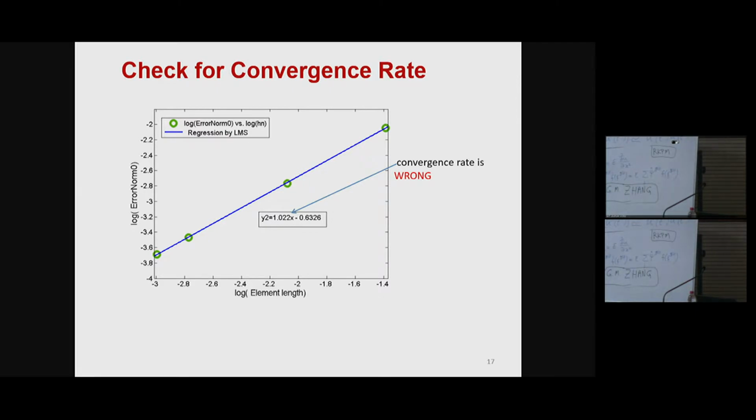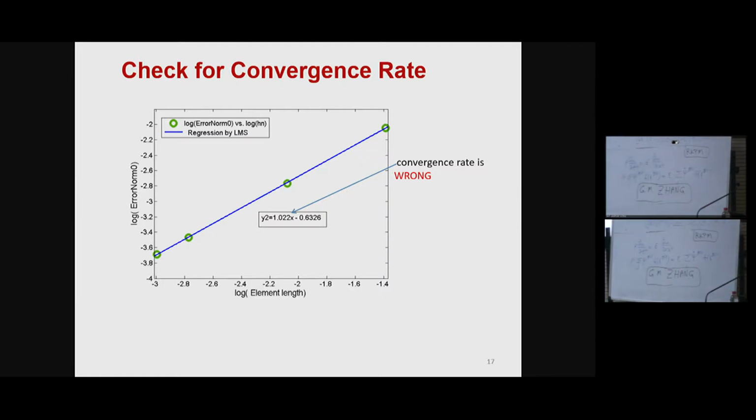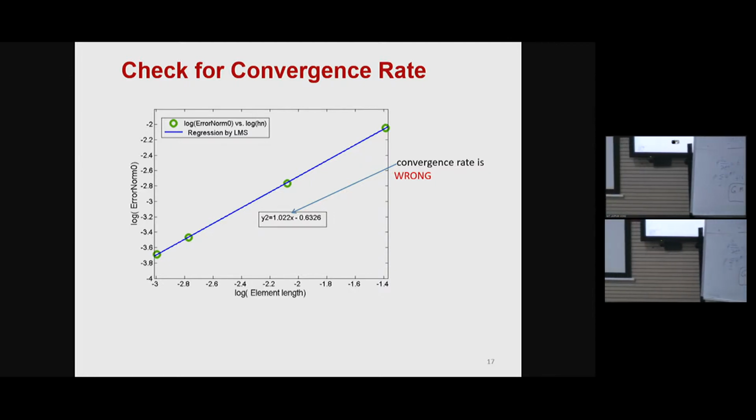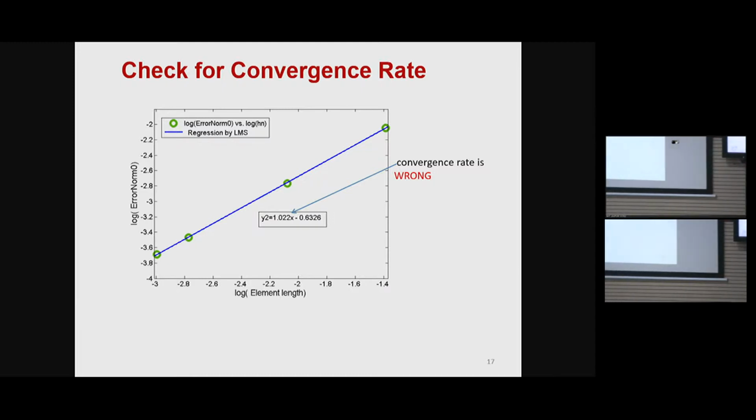The critical edge. Well, I don't know what is critical, but whether it's critical or non-critical, stresses at the edges are not correct. You should find stresses at the interior and then extrapolate to the boundaries. You can, but they are not good values. You should not find stresses at the boundaries of an element, period.